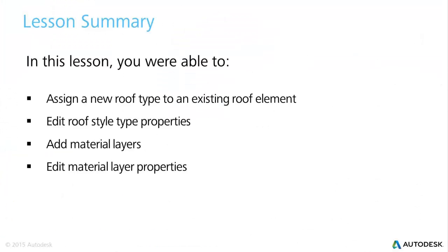Let's review the learning objectives for video 7. In this lesson, you were able to assign a new roof type to an existing roof element. Next, we created a new roof type, added material layers to that roof type, and then finally applied material layer properties to it.